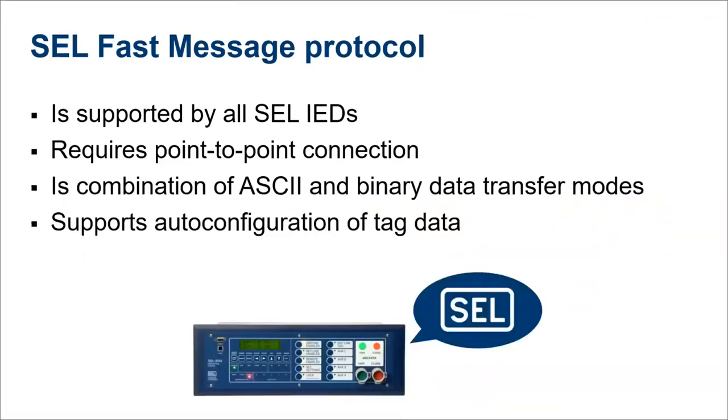SEL Fast Message Protocol is one of the primary protocols used by all SEL IEDs. It is supported by every one of our relays. It requires a point-to-point connection, such as RS-232, or a TCP port connection through Ethernet tunneled serial connection. This protocol is a combination of ASCII, which is text that you can see in a terminal, and binary data transfer modes. This allows you to have access through a terminal simultaneous with data transfer of binary information.